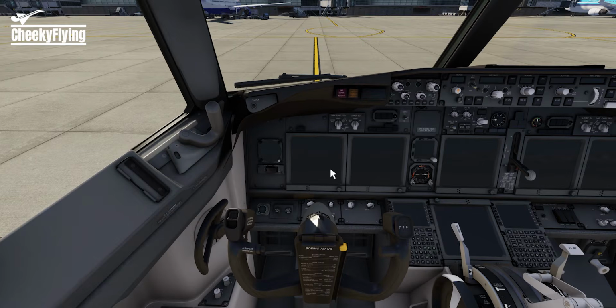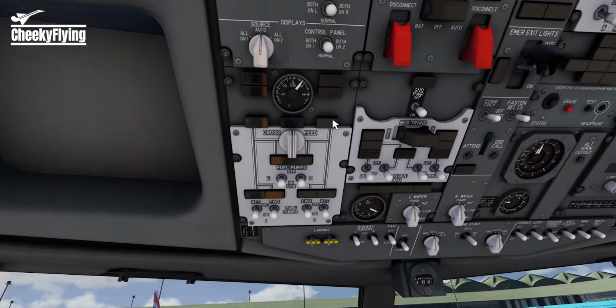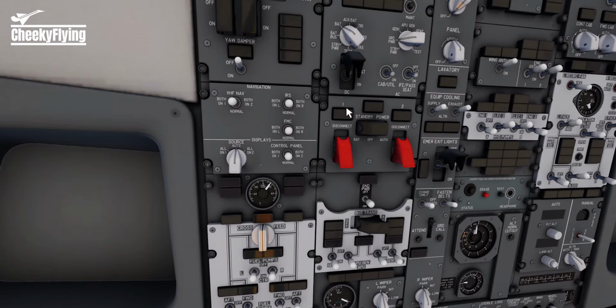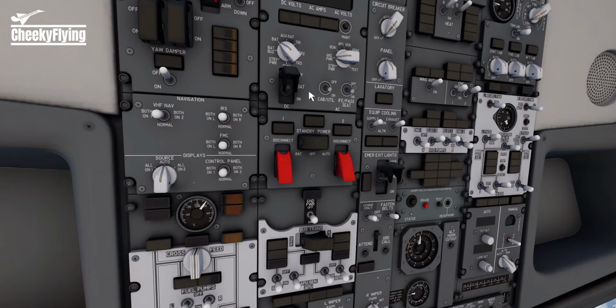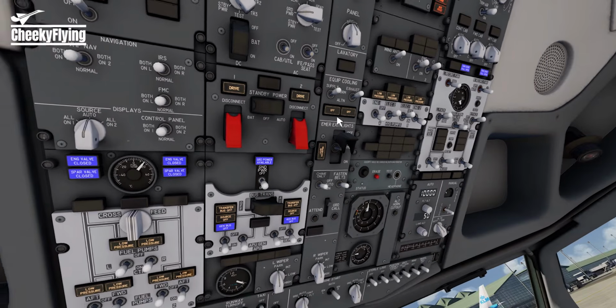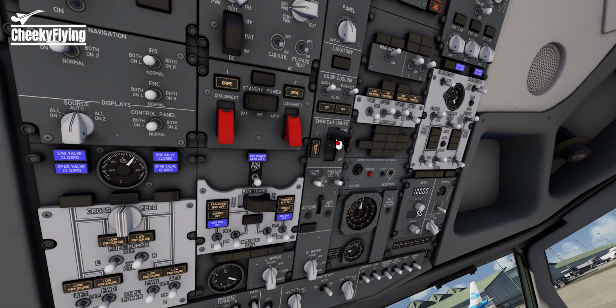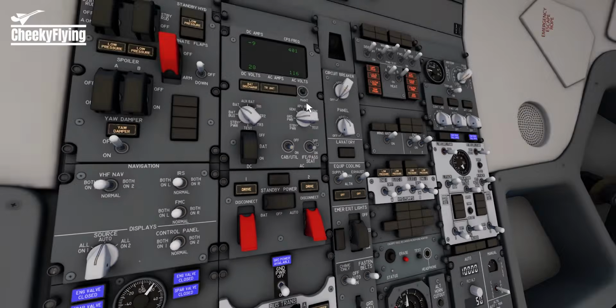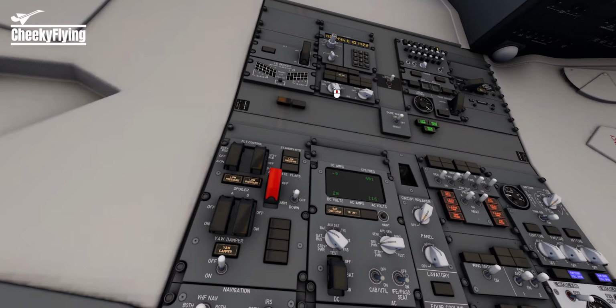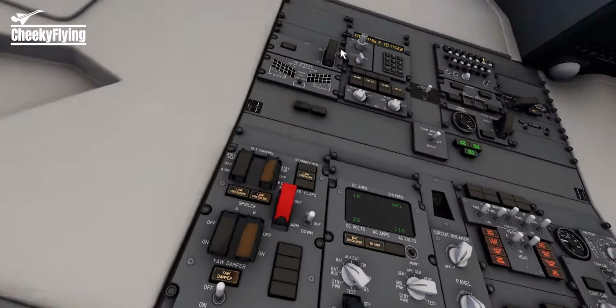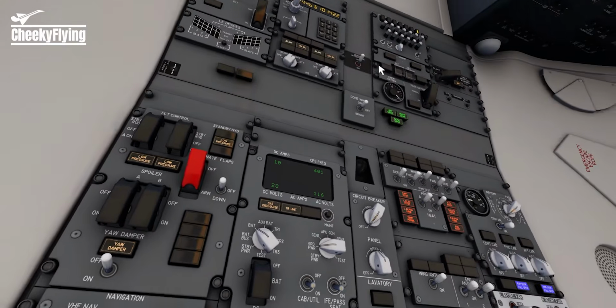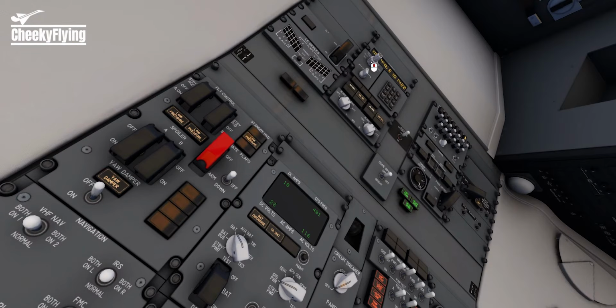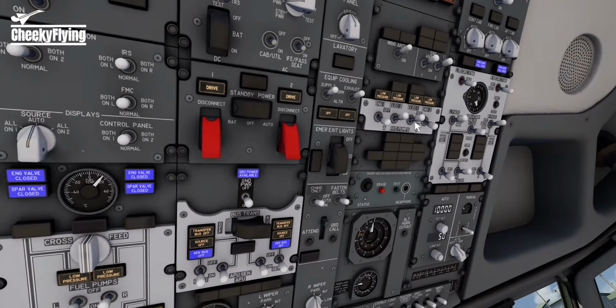Anyway, so let's start up the aircraft. So same routine as the Zibo and the default plane, which I have a tutorial for on the channel, you can look for that. So first we'll start with the batteries, and now the aircraft is turned on battery power. Close the cap here. Oh, there we go. And go up here and put on NAV. Yeah, NAV. And also, I'm not a fan of how the camera works in this simulator, but we move 1, 2 to the heading and STS, so it's 2 minutes to align, not that long.